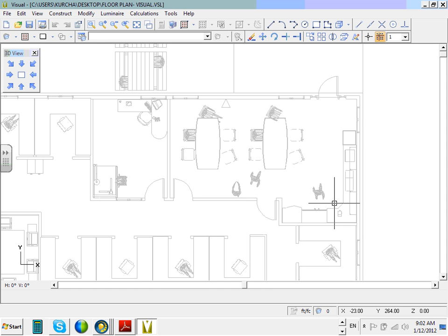Okay, if you guys look at the receiving room, what's that lunchroom here? Receiving corridor, conference, lunchroom. Lunchroom is 119. Everybody can see it? Lunchroom is 119, guys, and they want us at a 25-foot candle average. 25 foot candle average for the lunchroom, okay?